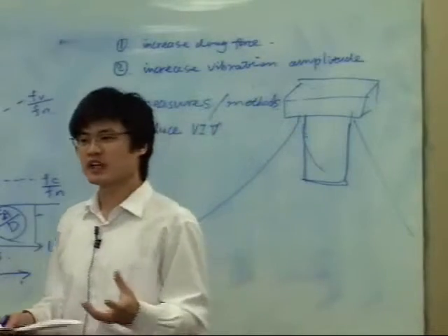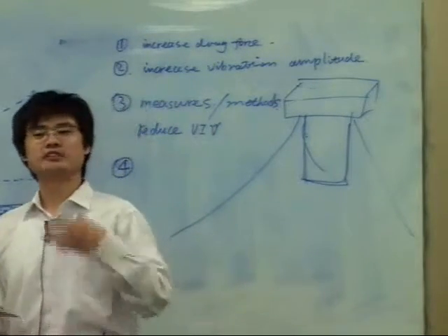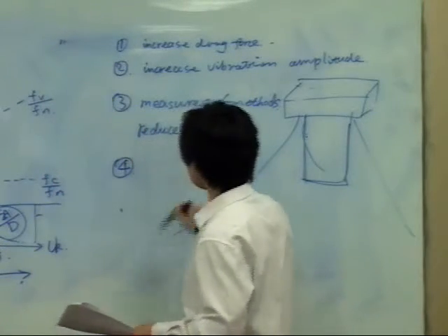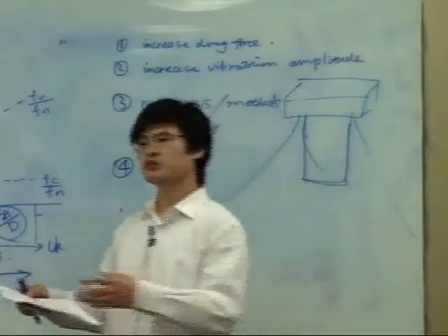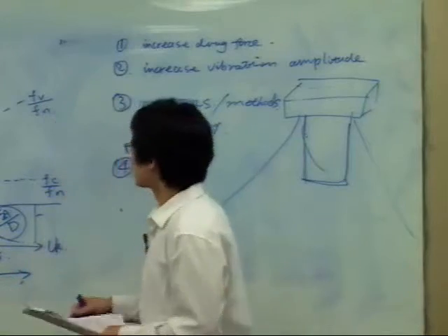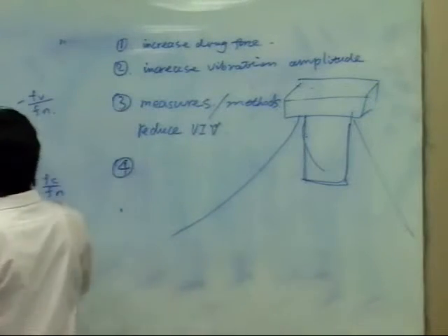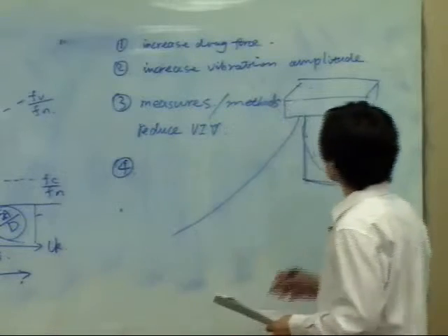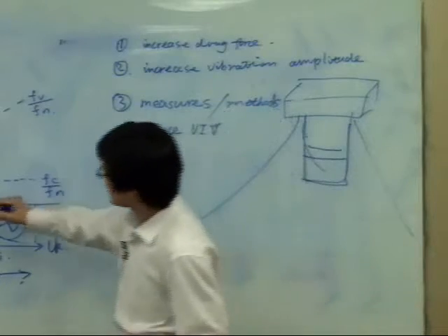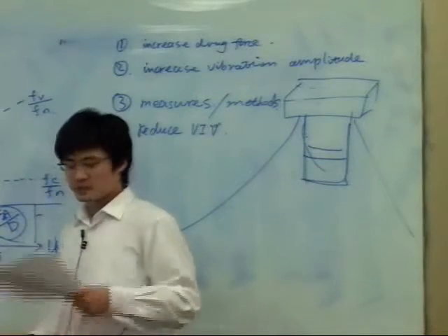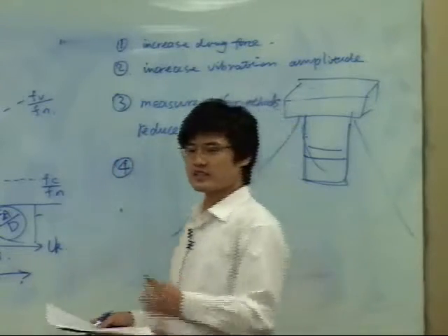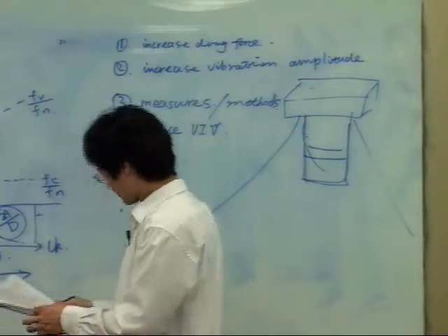If you want to harvest the current energy, like to generate power, you want large motions. You put a cylinder in the ocean or in the river. When the current goes through, you want the motion of this cylinder to be as large as possible. So they actually do some specific designs, by changing the surface roughness and other things to increase the maximum amplitude of the cylinder so that they can harvest more energy from the current.